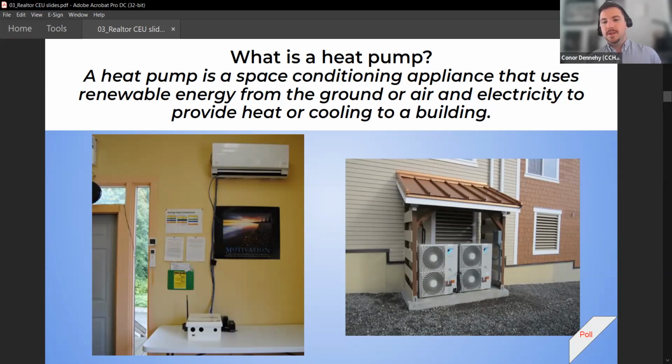With these mini split or ductless mini split systems, that same concept is happening. In the summertime, they'd be rejecting that heat to the outside, or for heating mode, they're trying to extract as much heat from the outside as possible. That's why in a cold climate, they don't necessarily work as well, because the colder it gets, the less heat is available outside to use. These machines take that heat that is available either in the air or the ground or the water, and then through the refrigeration cycle and the compressor, they step it up with some electricity and it turns into usable heat for yourself, or cooling, like I said.